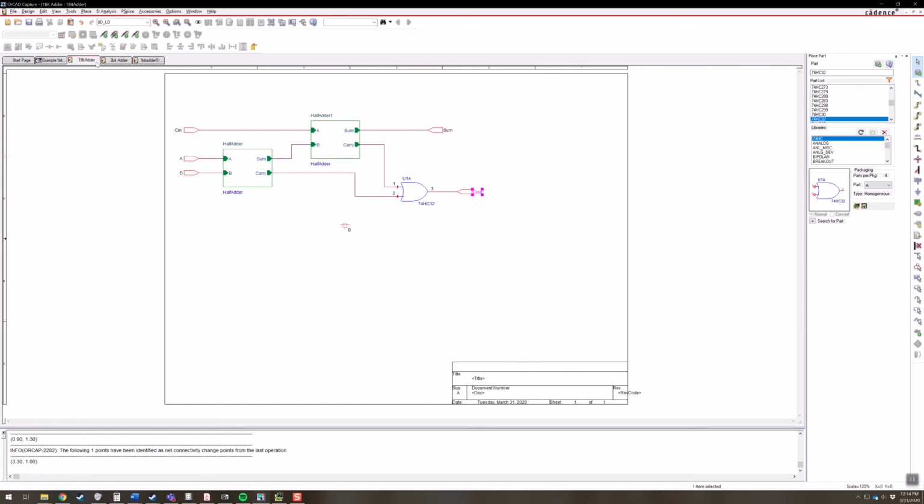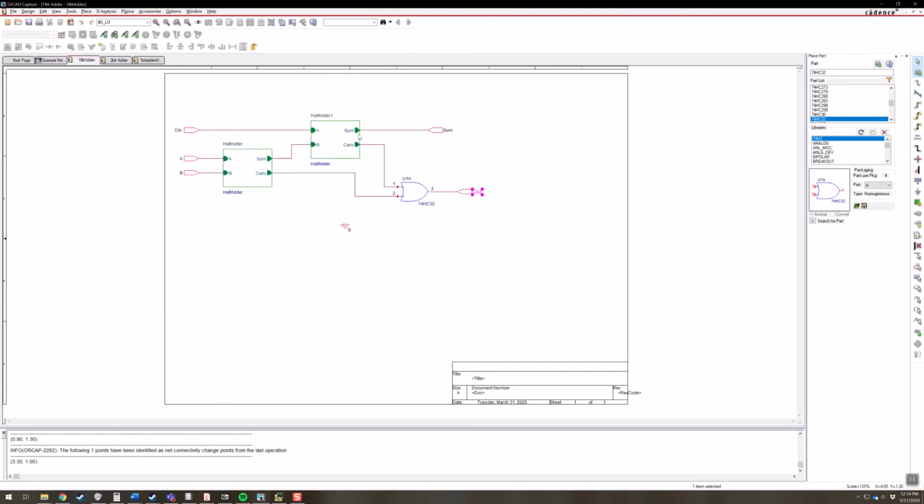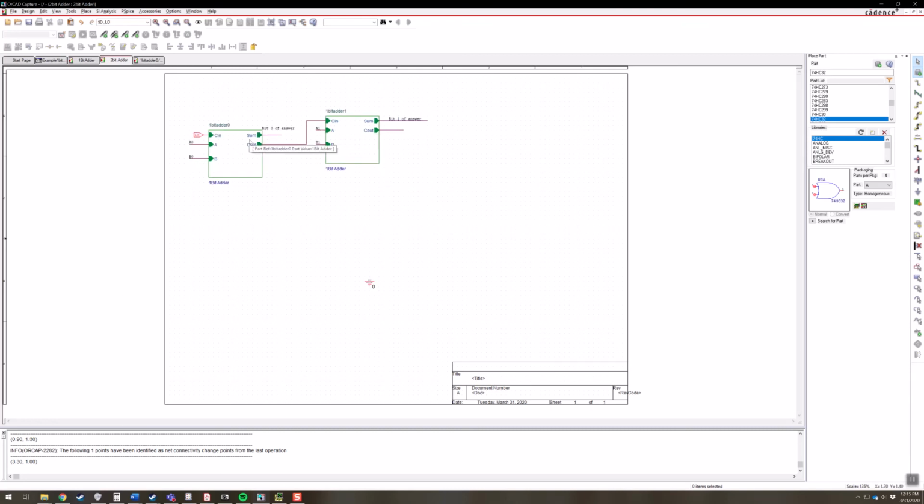And now here, what we've done instead is we're saying, okay, I've got my half adder here, it's 2 components. Then I've got 2 of those, so really there's 4 components going on here, plus a 5th one for the OR gate, so that's 5 components. And then for the 2-bit adder, there'd be 10 circuit elements here if we were to draw it all up by hand. So that's the advantage of hierarchical blocks, is that they can simplify your diagram significantly. All right, so that's what we'll be working on.